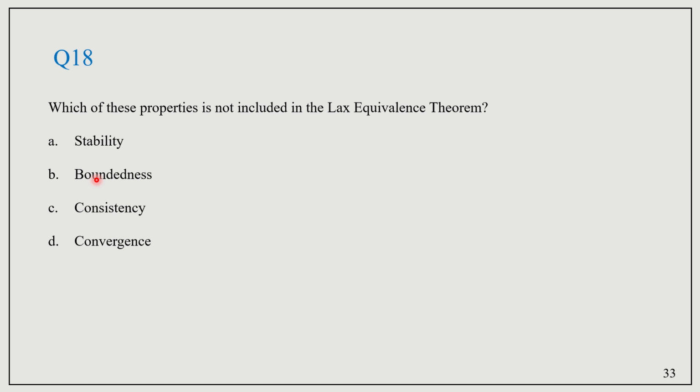So what is the Lax equivalence theorem stating? It states that stability and consistency are enough criteria for the system to be converging. When we want a converged solution, we should ensure that the schemes we are using are stable, and we will be getting consistent solutions.